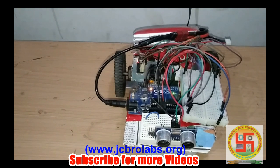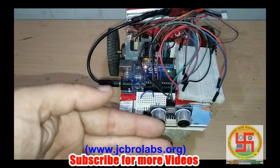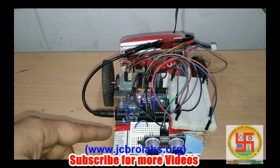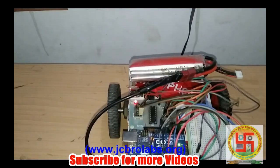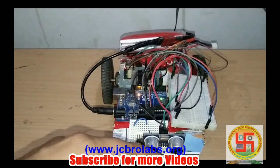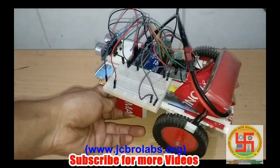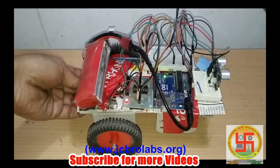So this is our final assembled robot prototype. Here we have the ultrasonic sensor, connected in front of the robot in order to measure the distance from the obstacle. Here we have the Arduino, and we have provided the power supply from this lithium ion battery. From this Arduino board we have provided VCC and ground to this breadboard, and from this breadboard we are providing the power to this L293D driver circuitry, to this ultrasonic sensor and to the board. So this is how the robot looks in assembled form. Let's have a slightly different look. It looks like this, and now we will write a program for our algorithm, and then we will test it in real time.